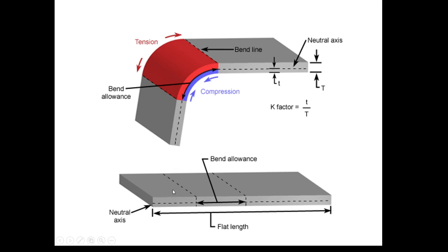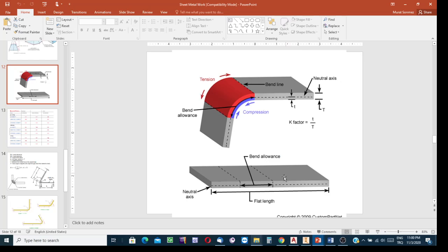while we are seeing the sheet metal work as unfolded, the length of the portion that corresponds to the round, or fillet, on this side is called the bend allowance. There should be such an additional material over there. Thanks to the existence of this additional part, the allowance can have such a round. Okay, so, well, here